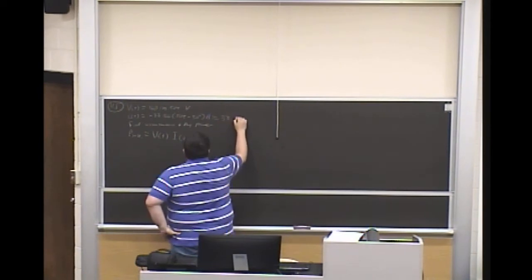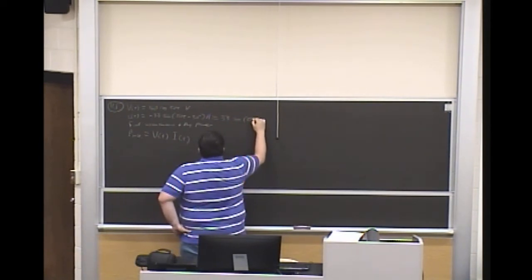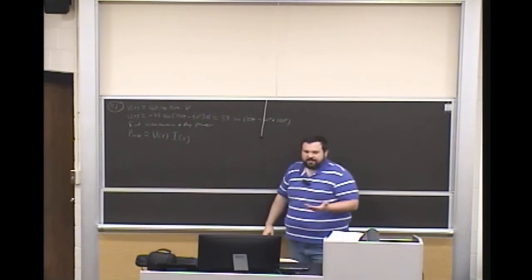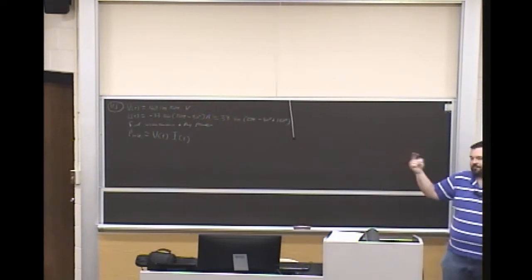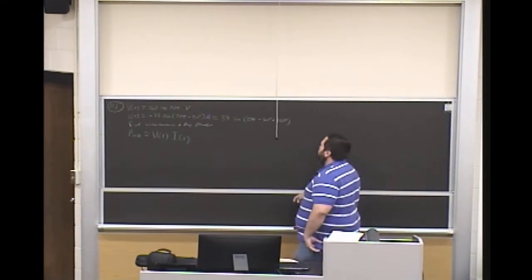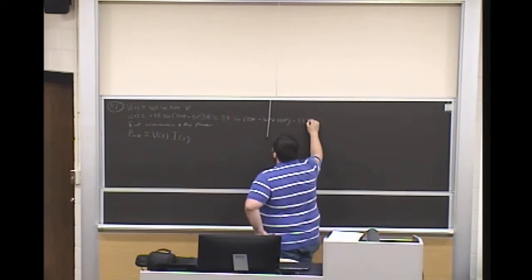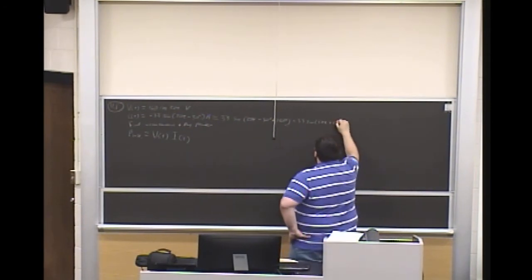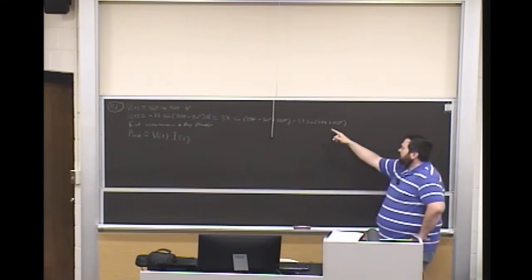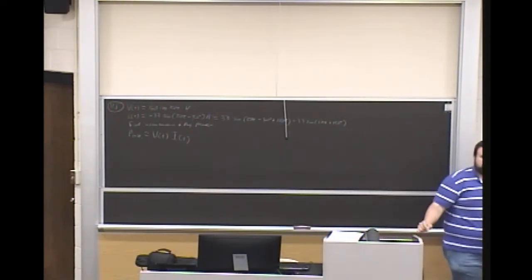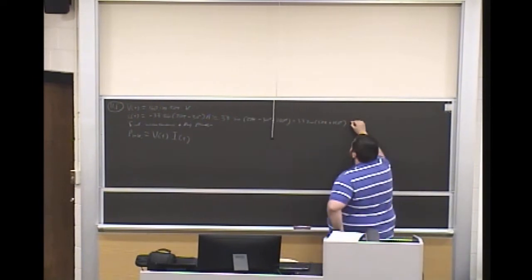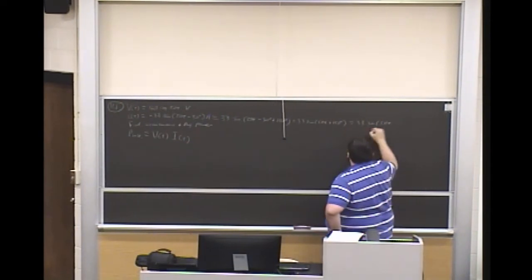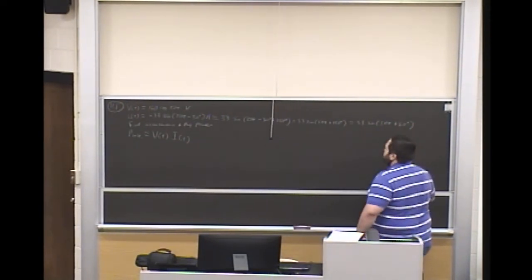So this becomes 33 sine of 50t minus 30 degrees plus 180 degrees. You can do just the same by subtracting 180 degrees; it doesn't really matter, you end up on the same side of the unit circle. So at this point we have 33 sine of 50t plus 150 degrees. Now, how can I convert sine into cosine? Subtract 90 degrees. If I take 90 off of this, I just get plus 60 degrees, cosine.